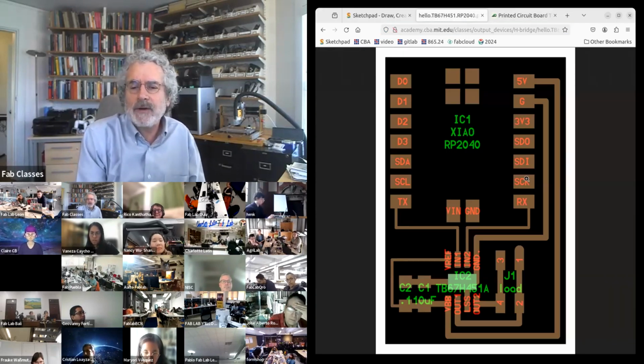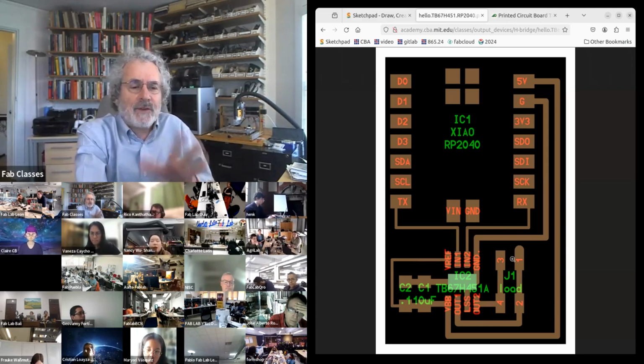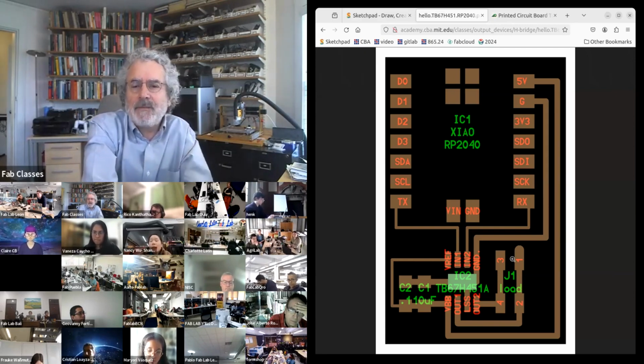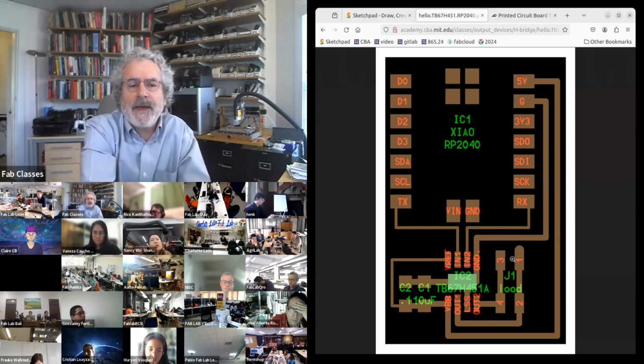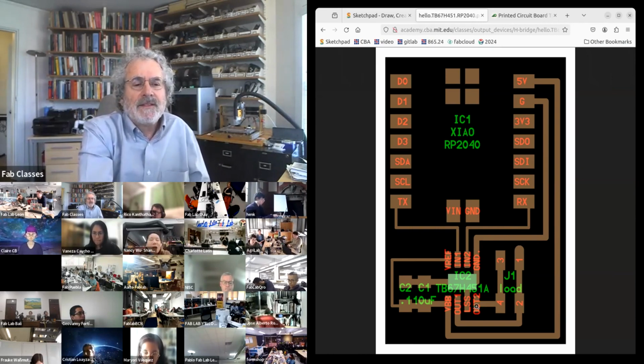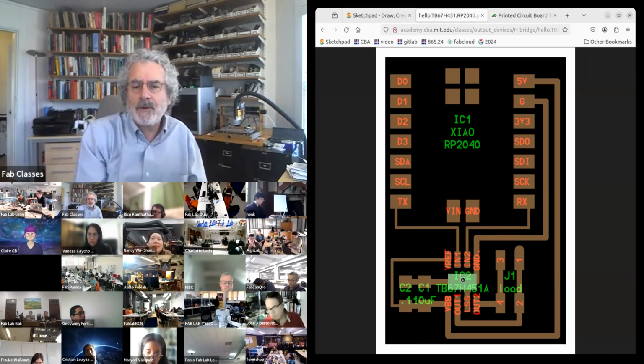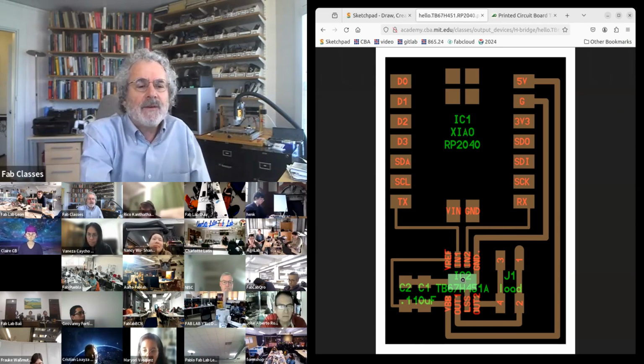You dissipate power and they heat. So for higher current paths, and for this example, I don't really need it, but I'm using it to illustrate, you can use heavier traces. The second thing going on is there's a thermal pad underneath, and I'm using that just to help couple heat away. And then you'll see I've got these 2 extra capacitors.